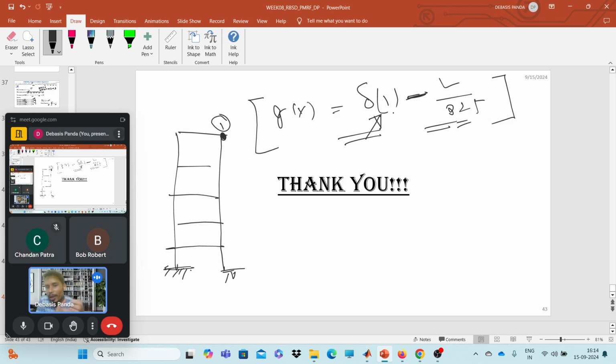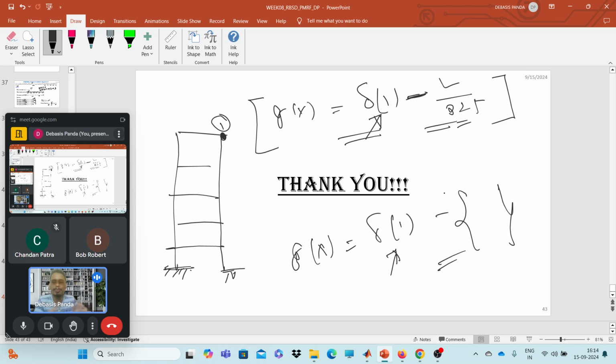Now, if you want to check with respect to the serviceable limit state condition, you form a limit state in which story or the entire structure. You just form a limit state for g(x) equals 0. I am calculating some del limit for the serviceable limit state, some requirements are there in our code. So as per that, you form your limit state, and as per that, you just call this del value and have the Monte Carlo simulation over.